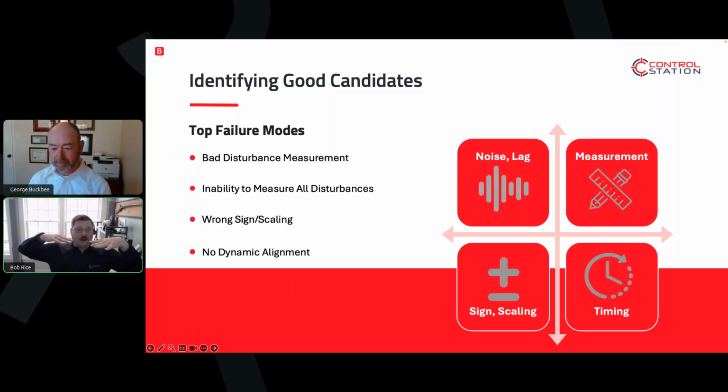Again, if I'm driving a Ferrari, I don't want to start accelerating a mile up the road, but if I'm driving a semi truck, I will need that time. So that dynamic, you want to make sure that correction arrives at the same time as the disturbance. Otherwise, it's really not going to work very well. And so when you're implementing feed forward, there are some challenges and concerns.